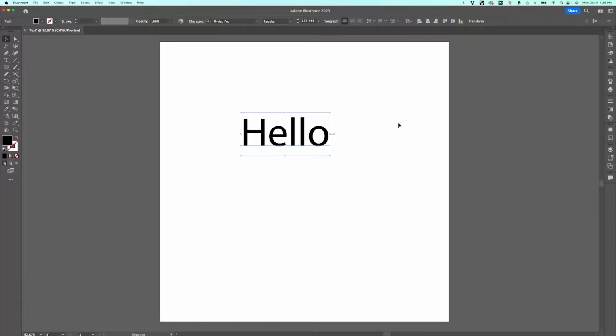Text is one of the easiest ways to create SVGs, but there is a lot that needs to happen before you can actually just export this as an SVG. If I wanted to export this now, it wouldn't appear in Cricut Design Space because it is still a font. We need to outline it. We need to do some other things. I'm going to go into an entire tutorial about how to use fonts in SVG design. It will be very in-depth, but for now, know that you can play around with text, but you're not going to be able to export it as an SVG quite yet.